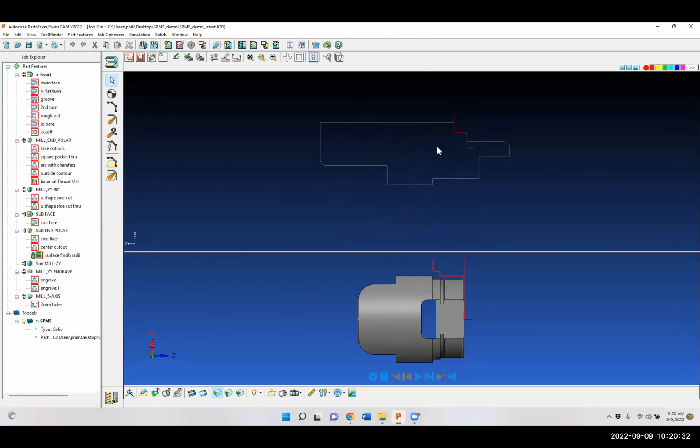Now here is the original tool path, and then I got the revision in saying we want to put a chamfer on the edge. So I can merely take the tool path and modify it, and just step it back, and then add the chamfer into the profile. And the chaining function is just like any other chaining function from any other software. Be nothing you have to worry about here.